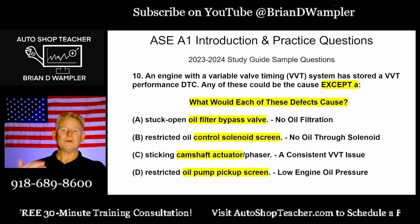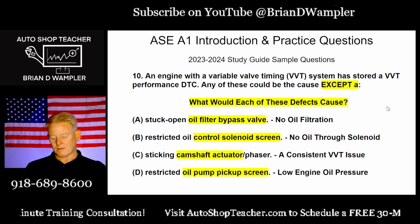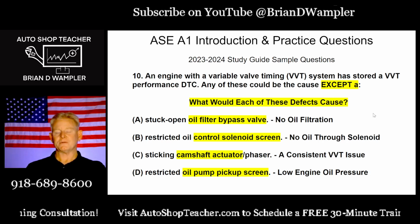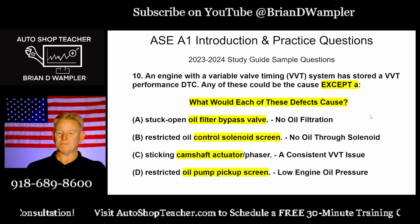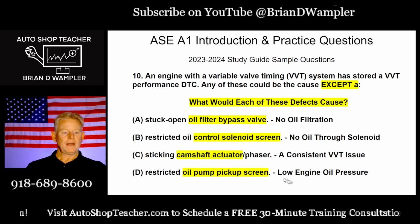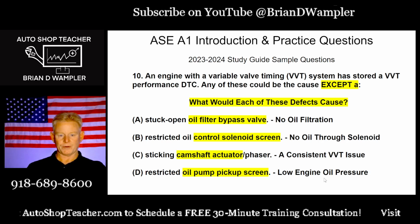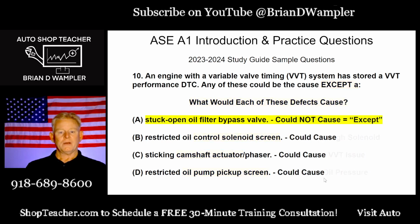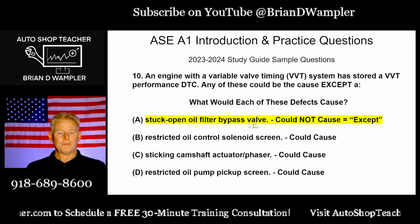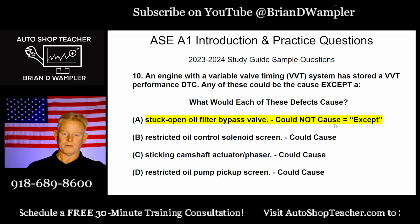We don't know, but we do know that it says it's stored, okay? Not trying to get into word semantics or into the A8 and L1 type of test questions, but just keep an eye out for little bits of information like that. And a restricted oil pump pickup screen. Well, we would have low engine oil pressure, right? So the stuck open oil filter bypass valve could not cause, so then there is your accept.